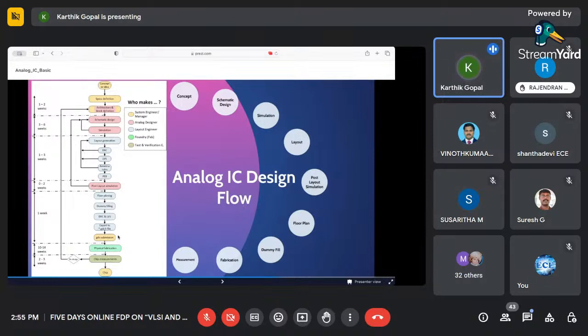So in terms of the manufacturing thing, the layout engineer will give a file format which the industry can understand and start working with. In the industry, once you give the file, they won't check what the design is. They just get the design and check whether it meets their manufacturing criteria or not. That format is called GDS, .gds. So this is called GDS submission. This submission means we give it to the foundry.